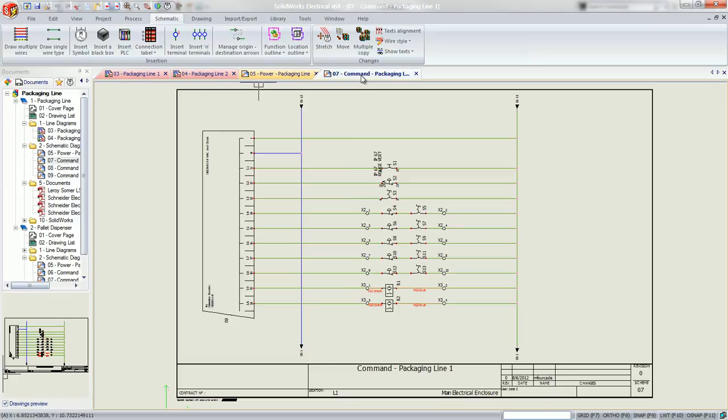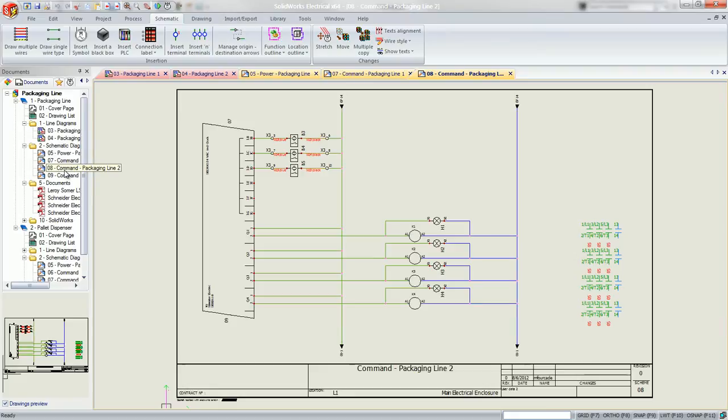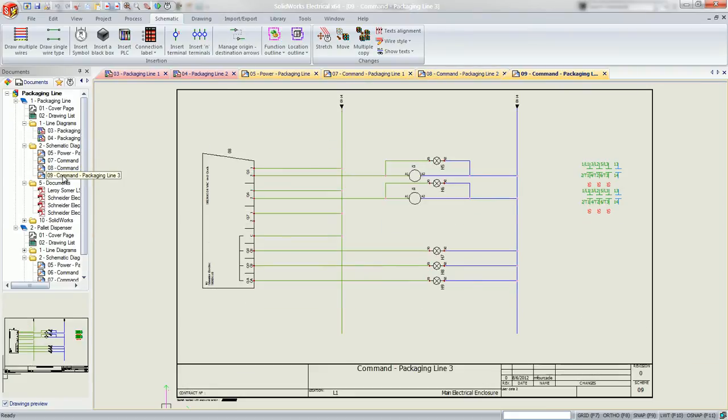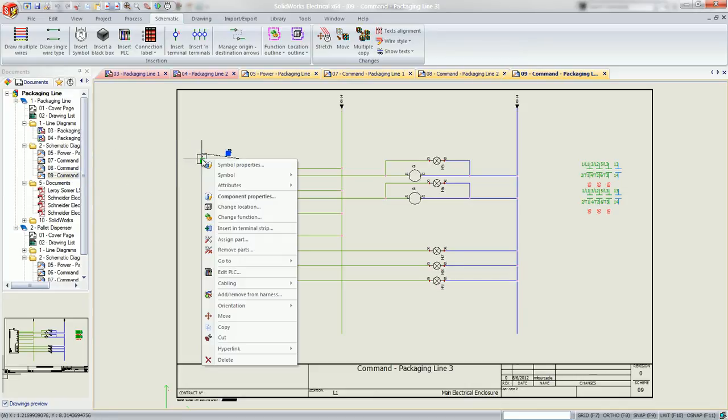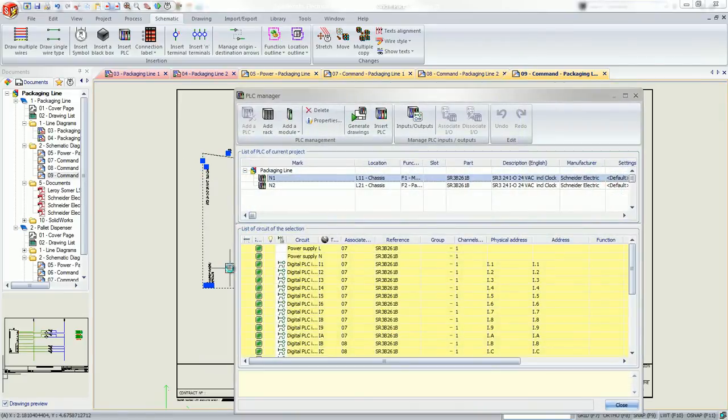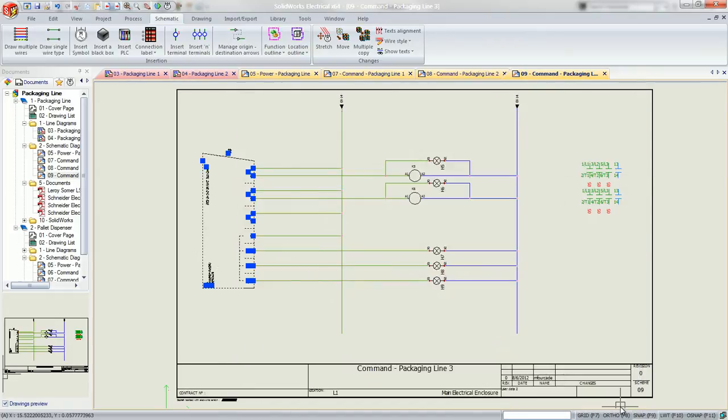The functionality of the conveyors and lights is controlled virtually automatically using the sensors and a simple button human interface. SolidWorks Electrical enables you to tackle the development of complex electrical systems with specific tools. PLCs can be inserted or customized like any other parts, and the PLC Manager offers a simple yet concise way to modify it, list the input and output, type description, add modules, or generate drawings. In addition, macros can be used when inserting a PLC into your schematic to automate the process further.